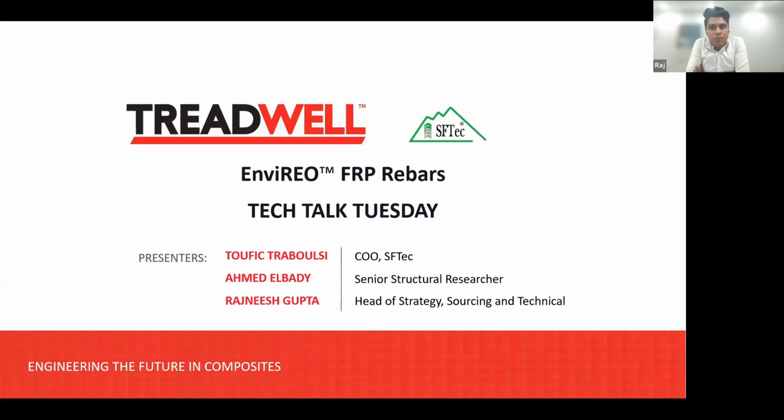Now, how are FRP rebars made? Just like other FRP or GFRP products, they are made of two high-level materials: the reinforcement, which can be glass, carbon, aramid, or basalt, and the matrix, which is resin, such as vinyl ester and epoxy. They are made in a process called pultrusion, which is very similar to extrusion, where the glass fibers are impregnated by the resin of choice and then passed through a heated tool, in this case round in shape, and through heat the curing happens and the thermoset is formed.